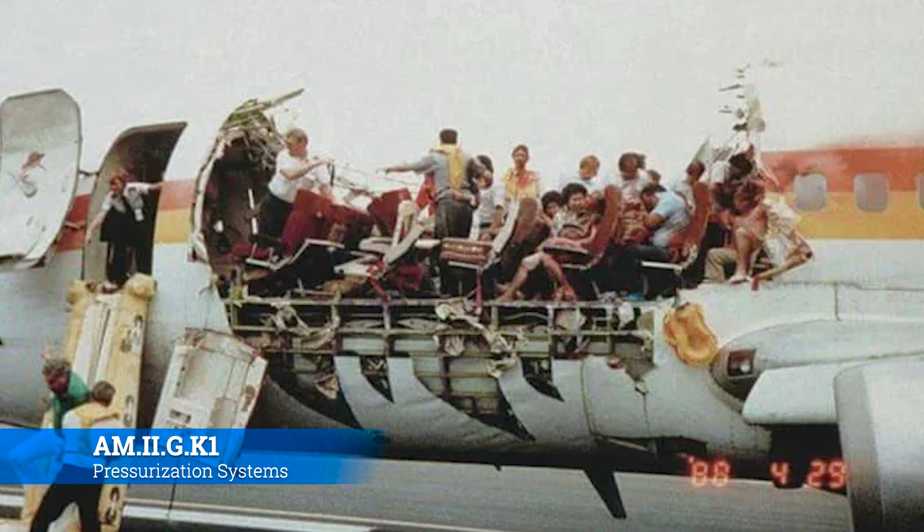It didn't blow it off. It just caused the rivets to pop, and it popped up. When it popped up, it caught the air, and the air pressure ripped that section of the aircraft off. And you notice that it folded back right there, right in front of the wings. And kind of an aside, this is also the reason why you always wear your seatbelt whenever you're flying on an airliner. Notice how many people are just sitting there. The reason they were sitting there and were able to survive is because they were wearing their seatbelts. There's only one person that died in this incident.